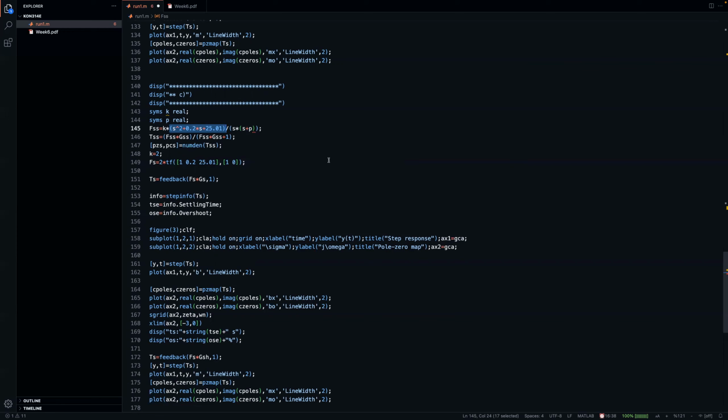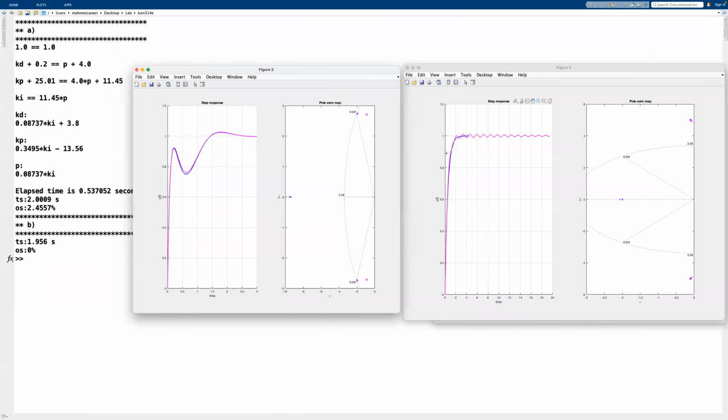It starts from 0, starts from minus P. They coincide at minus P divided by 2. Then we have our asymptotes, and they will tend to j infinity and minus j infinity. And we know that this should occur at sigma equals minus 2. Why? Well, our settling time is going to be satisfied, and that settling time lies on this line of minus 2.